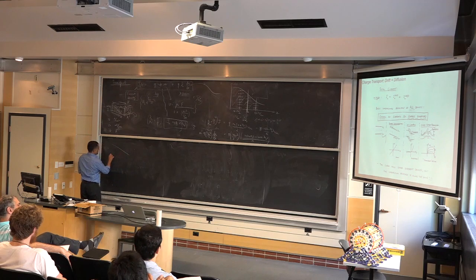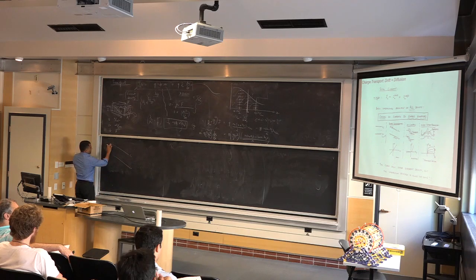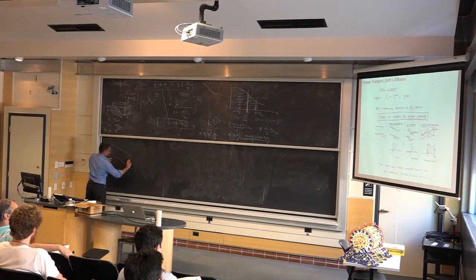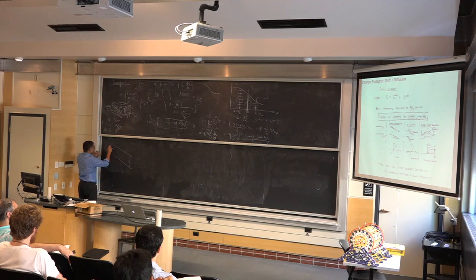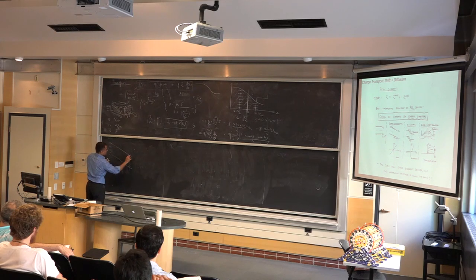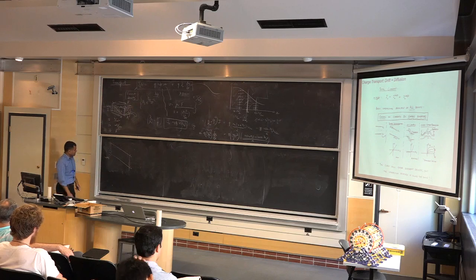And if you want to look at the microscopic picture of this situation, the energy band diagram looks like this, right? EV, EC. But really, what's going on is you have formed two contacts to these two regions, the two metal electrodes that are connected to the semiconductor. Okay? And the metal electrodes have energy levels that are filled up all the way to, let's say, if you have connected to the N-type semiconductor, you have electrons in the metal that are filled all the way to that level. That's the Fermi level of the metal. And then you have electrons that are already in the conduction band because you have doped it with donors. Right? You have pushed up some electrons into the band.